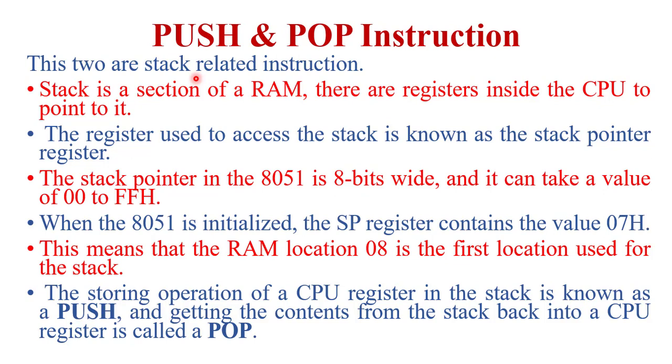And here we store data temporarily. So here I have written, stack is basically a section of RAM in the 8051 microcontroller, or we can say that it is a block of memory in the 8051 microcontroller which is used to store data temporarily, and there is a register inside the CPU to point to that memory location or stack.